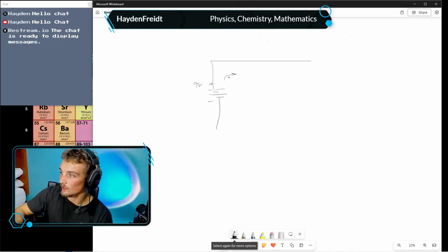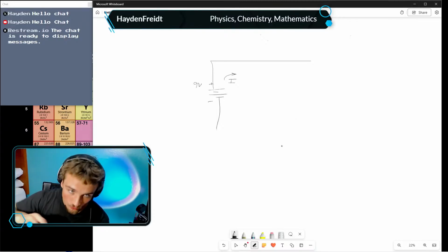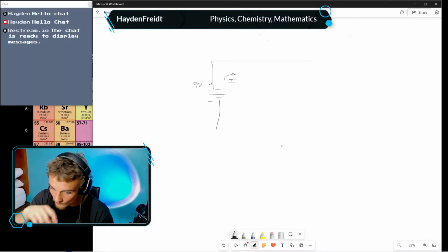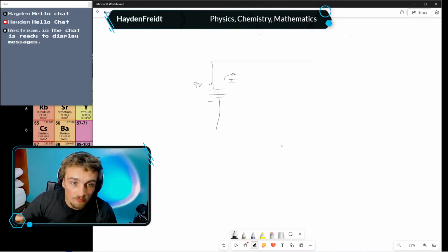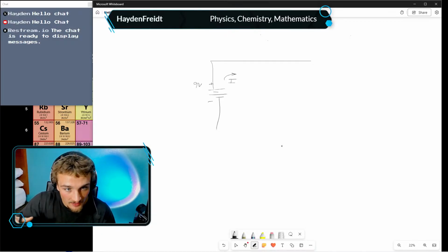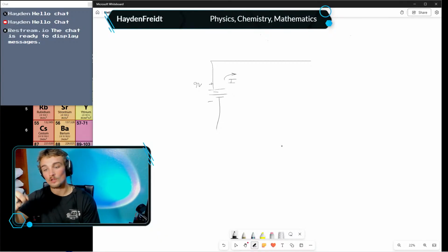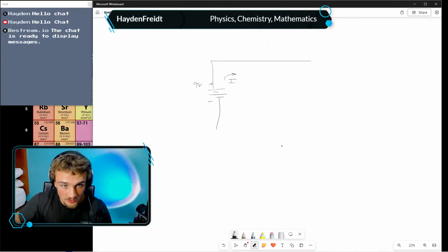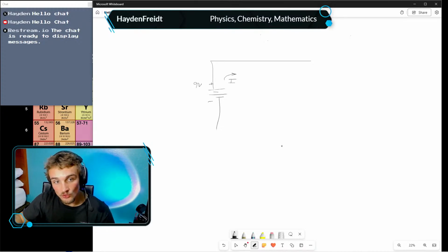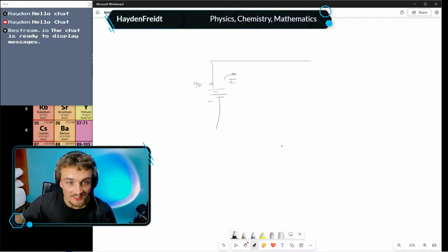Yeah, so we'll make it capital F. Boom. Okay. All right. So what I need to do is we're gonna have part of the circuit operating the gate, and that determines when the transistor turns on and off. And then we're gonna have another portion of the circuit that's going to be a voltage divider, that's going to supply the LEDs.